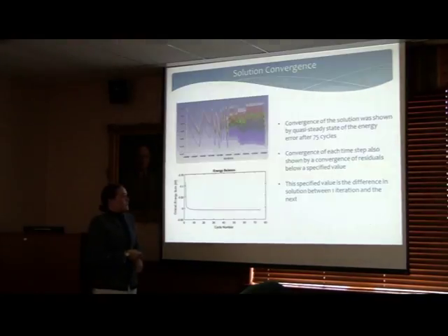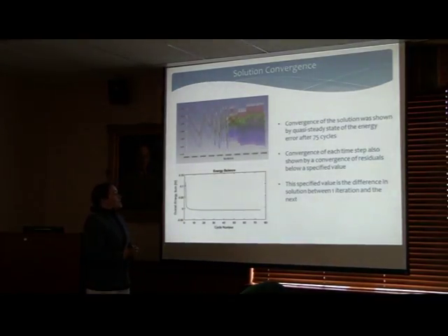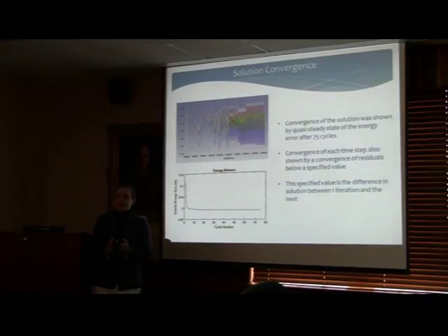So post-processing. Post-processing starts in Fluent as well. This is what you see while your simulation runs for hours and hours and hours. What this shows is, within a time step, so even smaller than cycles, we broke the cycles down into time steps. Within each time step, you're going to run 30 to 40 iterations.